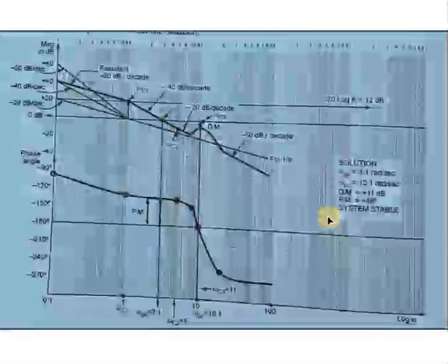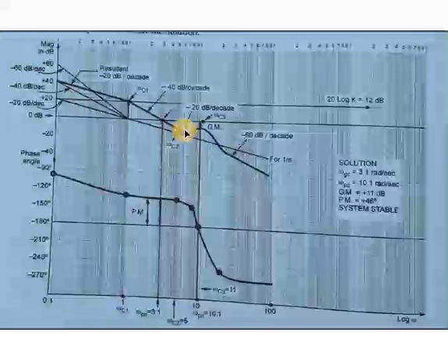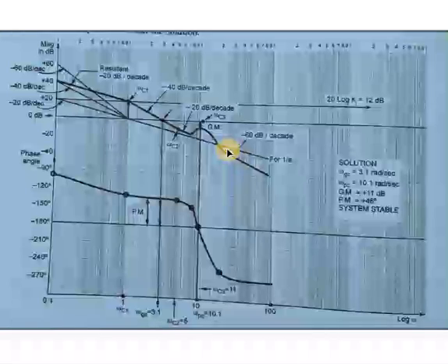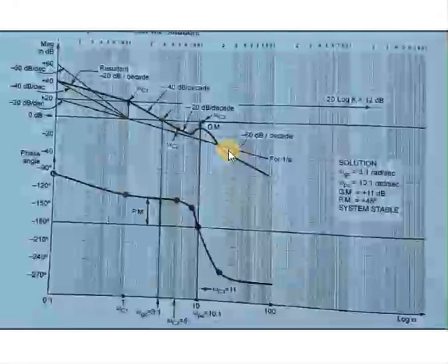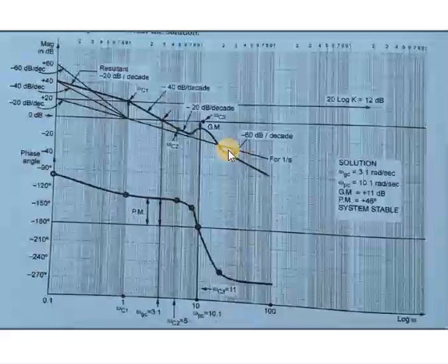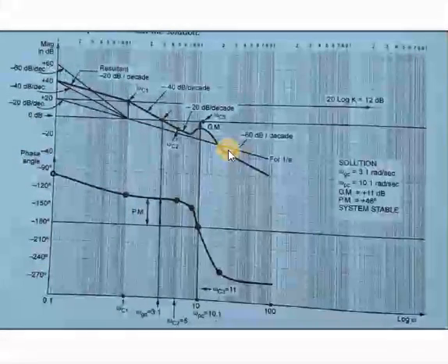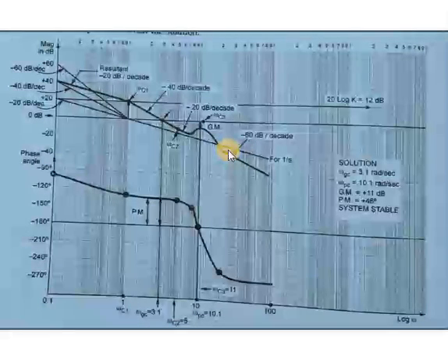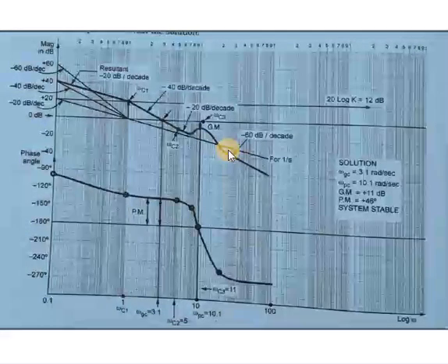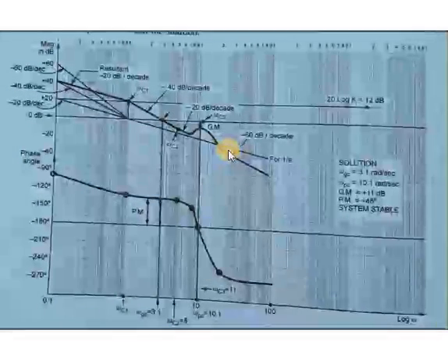Okay, so here the only difference is if you have the quadratic pole or zero, you need to calculate the correction factor and you need to give that excitation near that respective frequency. Okay, so these are some of the varieties of problems on Bode plot. Basically there are three types of problems you may get in your exam. First one is with a known k value. In the transfer function k will be given, with simple poles, a simple pole at the origin, or simple zeros. There you need to calculate gain margin, phase margin, omega GC and omega PC.